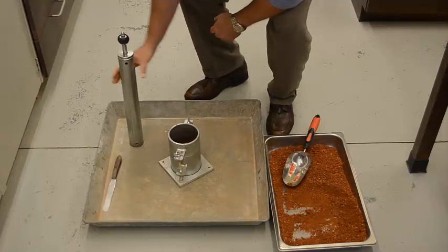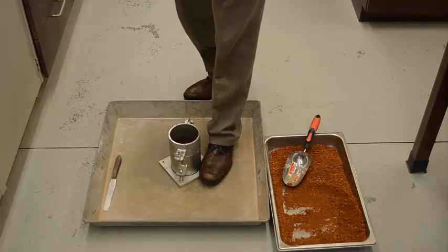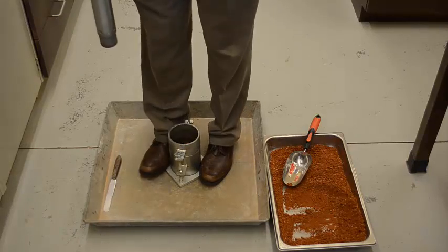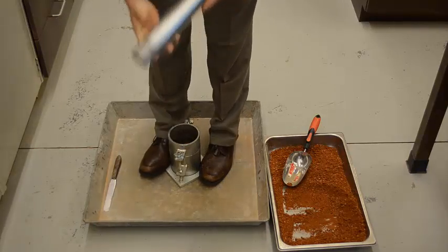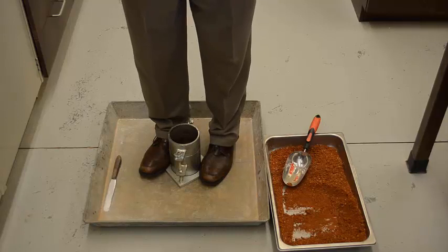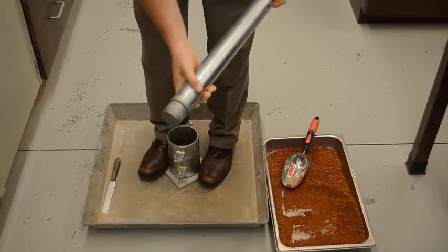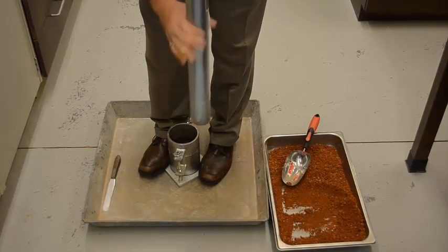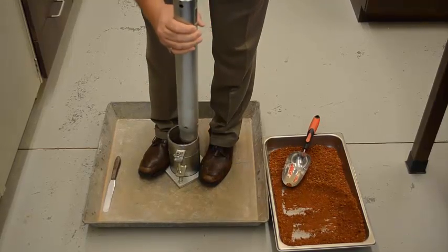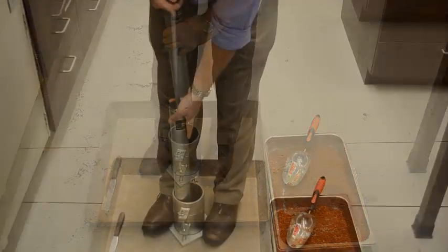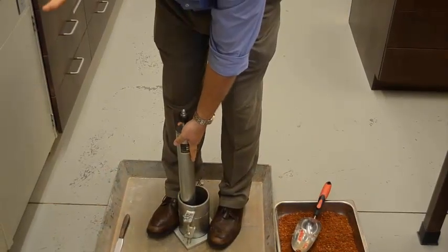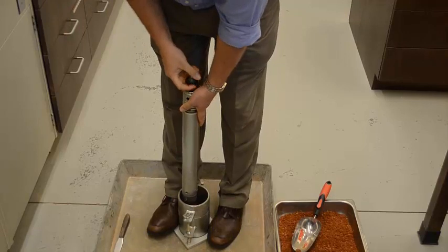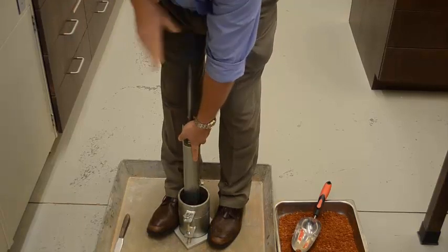And what I like to do is pack it down just a little bit with my hand before I get started. But I want to step on that mold so it doesn't go anywhere, and I want you to notice that the hammer has a collar around it, and make sure that it is clean every time you begin. And you extend that up, push the collar down onto the material, and let it drop by its own weight. Okay, then lift it up, move it around just a little bit more, and let it drop.